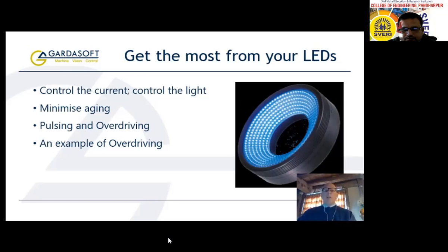LEDs are remarkably reliable devices, but their light output will deteriorate over time as a consequence of repeated heating and cooling cycles. Typically, an LED would be replaced when its output falls to below 70% of its initial rating. Driving an LED continuously will generate the most heat and create the lowest device lifetime. Switching the light on only when an image is being acquired by pulsing the light will minimize the amount of heat produced and significantly improve LED lifetime.